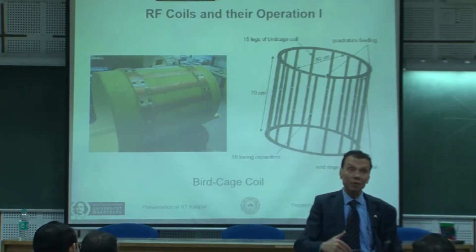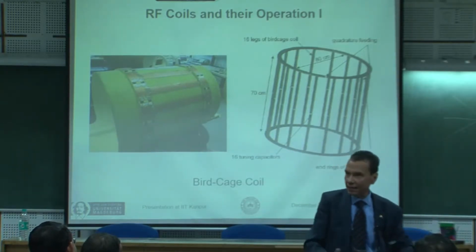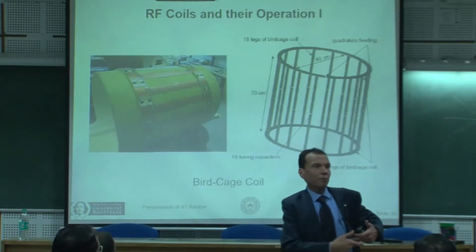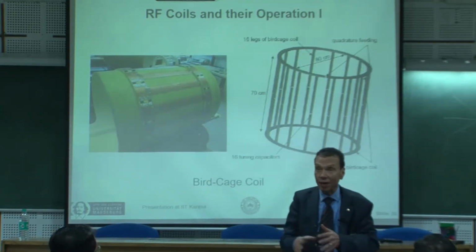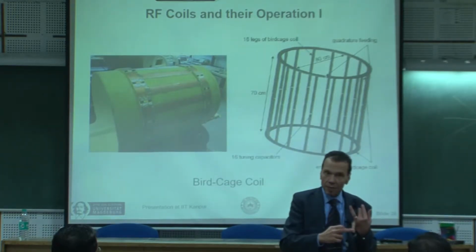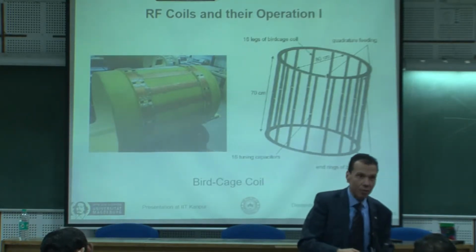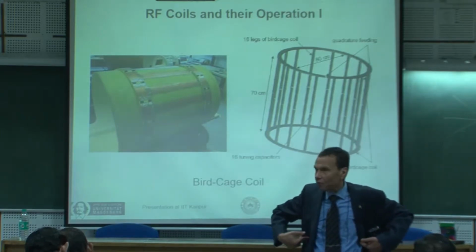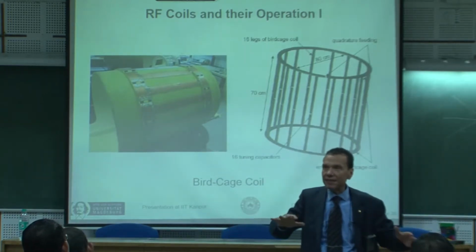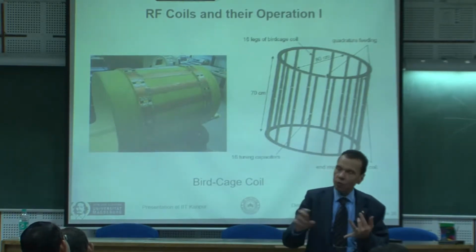Don't forget that using the ramps, you are also moving in a range, because with the frequency coding, you come from here to there with a certain bandwidth. All these are aspects to be considered in your design. You would like to have a high Q in order to have better resolution in the z direction, but not extremely high Q, in order to have a bigger field of view in one direction or the other. So these are maybe contradicting requirements. So let us take now the keyword high Q.